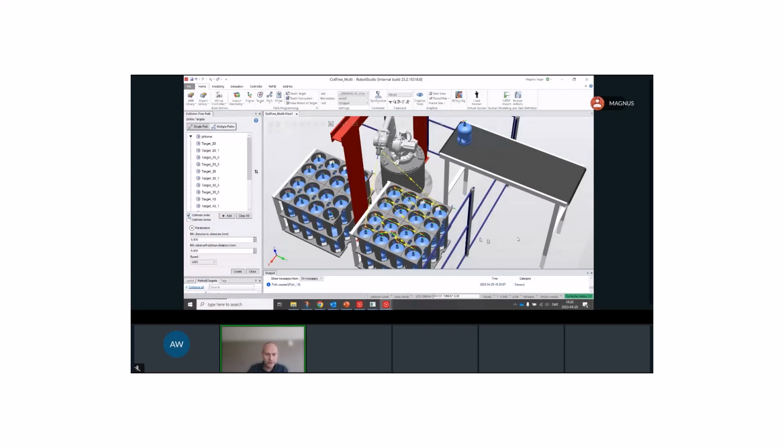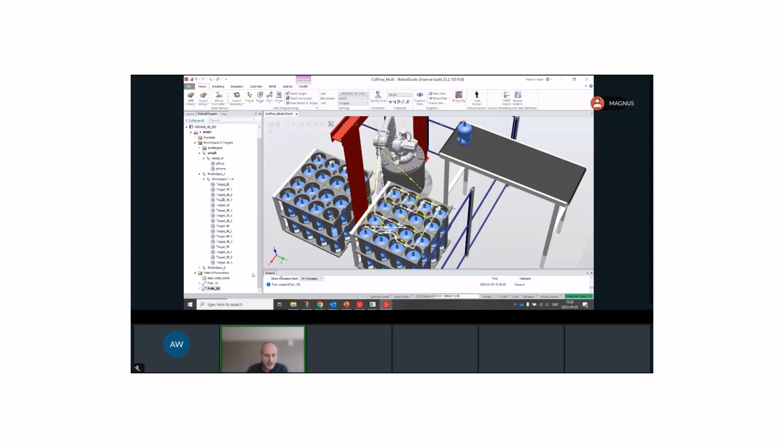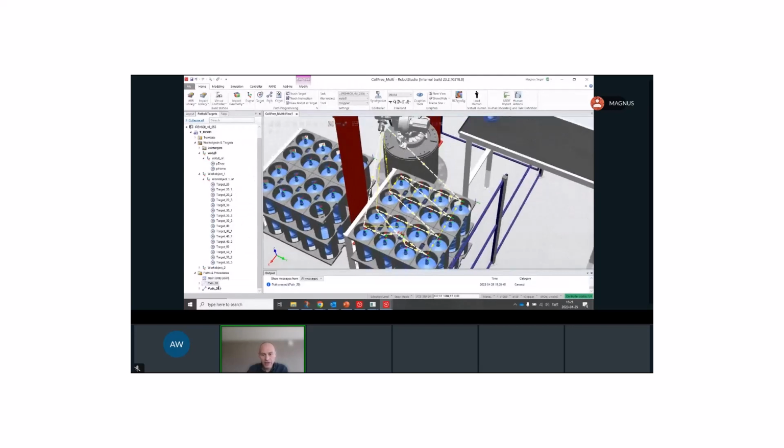So I just select this box, I press create, and what's happening now is pretty much like a traveling salesman problem, that we weight the different parts and we take the one with the least weight. And what we ended up with is this guy. So I just turn off visible the first one, and you can see that looking at this and you compare to this guy, you can just by looking with the eye see that this is way much shorter than the previous one. So you can also use the collision-free path planning to optimize the path in the shortest movement.